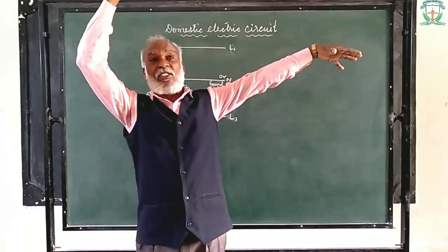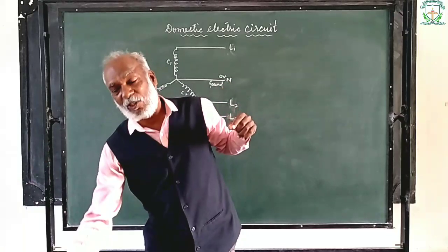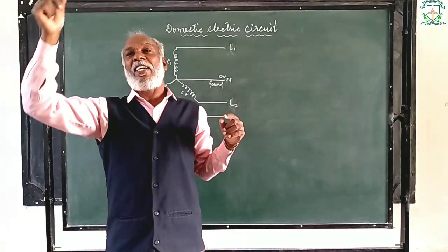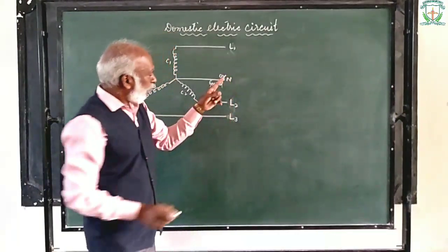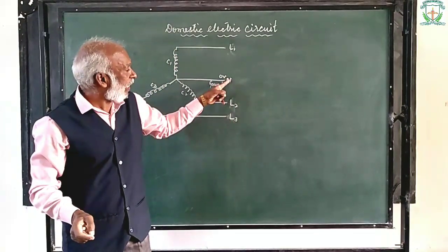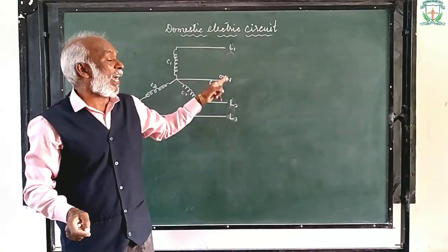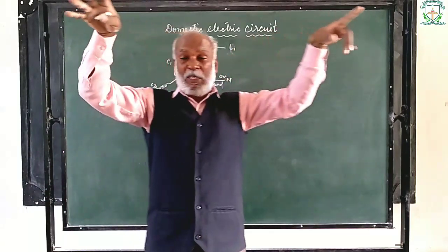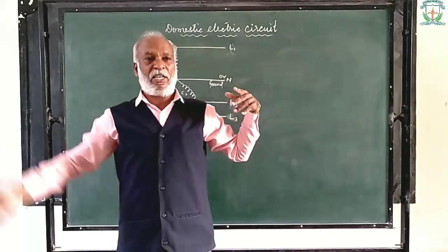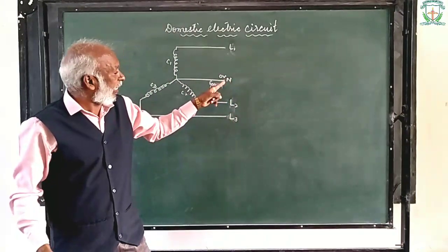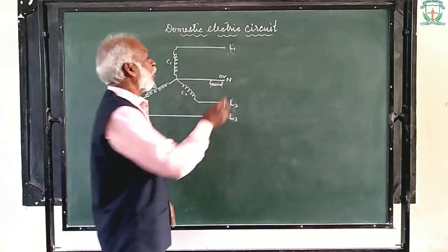See, in the generating station, one wire is grounded. The same wire is drawn from the earth near the transformer. So the potential difference between neutral and one of the line wires in the domestic area, residential area or business establishments or commercial area is 220 volts.